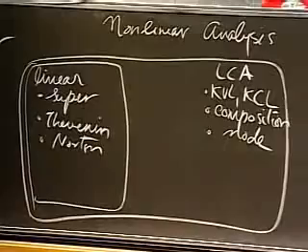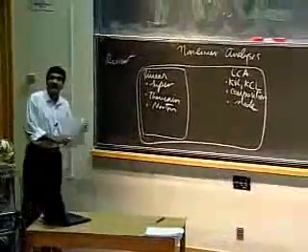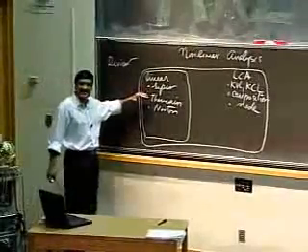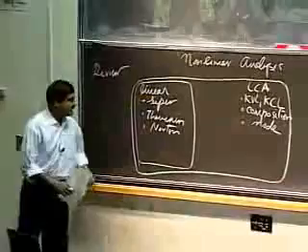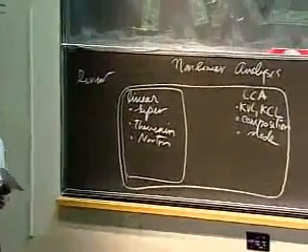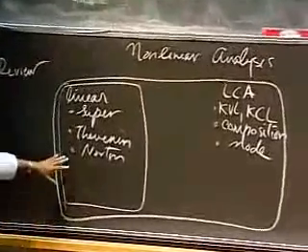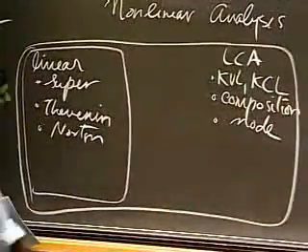Whenever you see a circuit containing 2 or more voltage sources or current sources, as a first step, think superposition. Okay? And these are very powerful techniques that let you analyze very complicated circuits very effectively. So after we did this, we said,